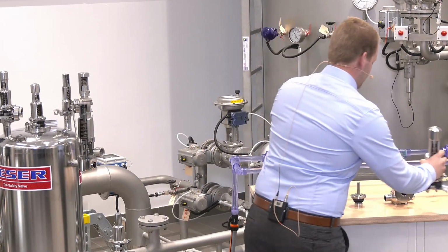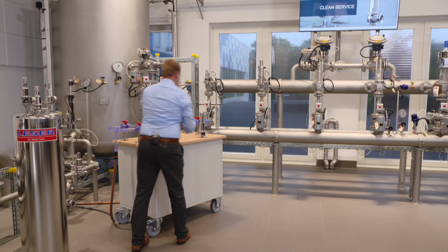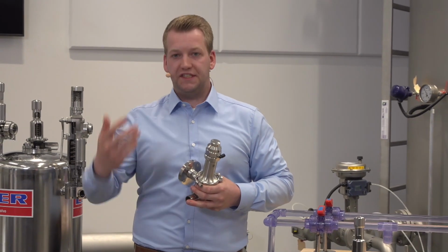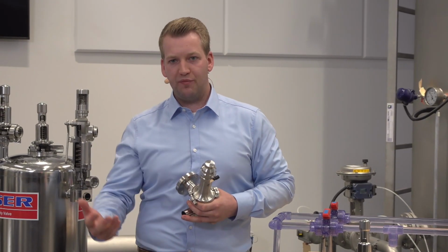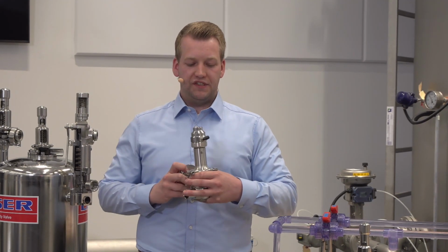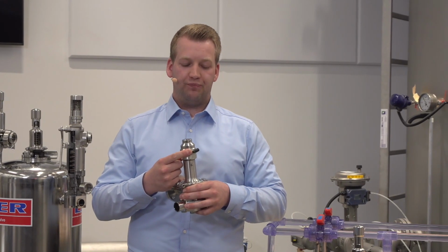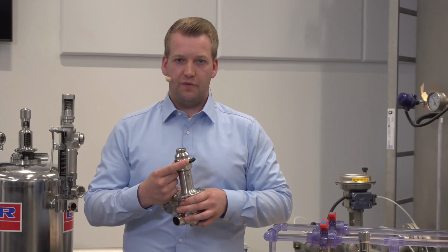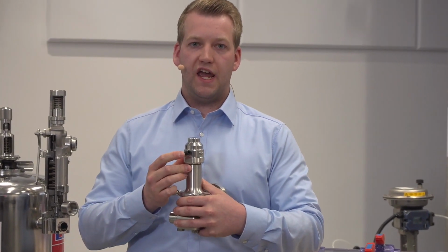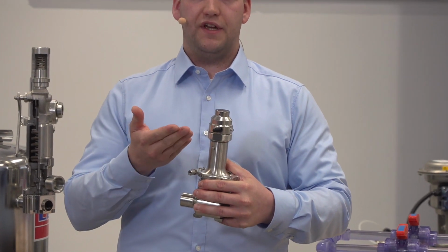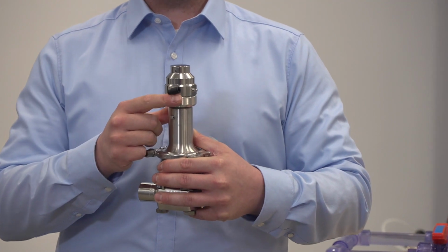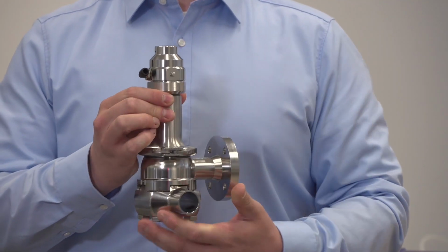The next advantage is if you want to have an automatic cleaning process. This means CIP or SIP: cleaning in place, and sterilization in place. For this we have designed a pneumatic lifting device. Pneumatic lifting device means that we can go over here with pressure air, and we can lift if you have your cleaning process automatically in your plant. We can open the safety valve with pressure air here on the top.